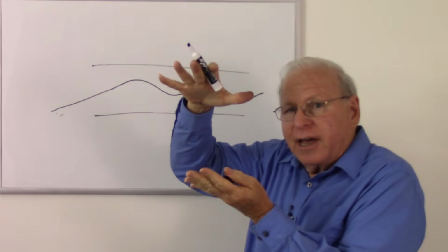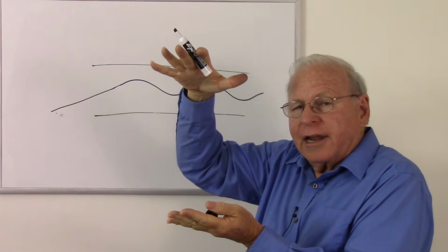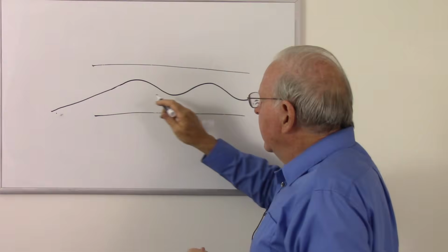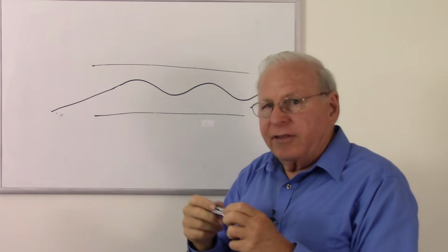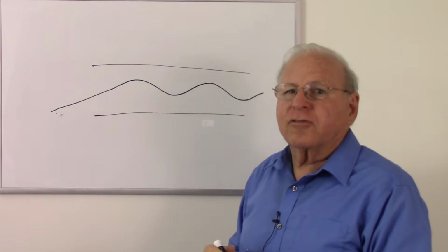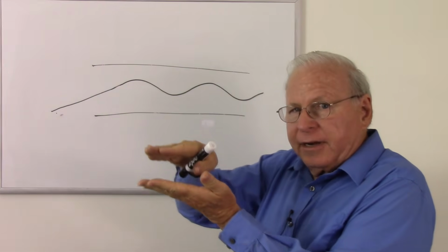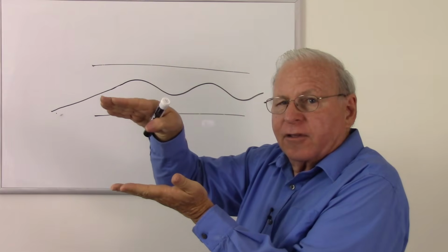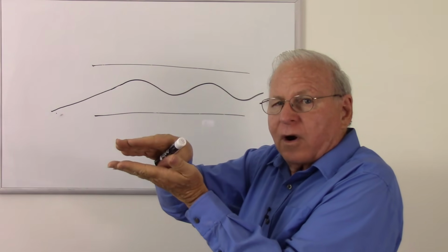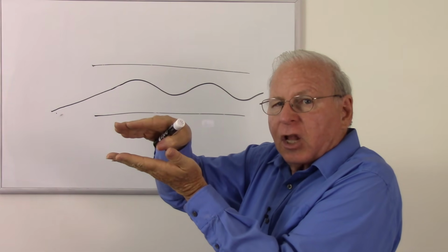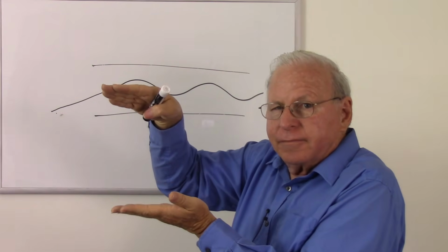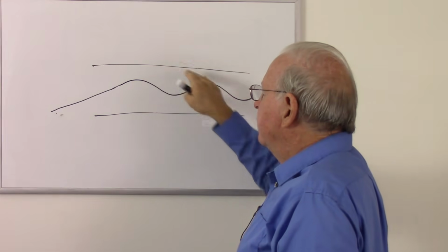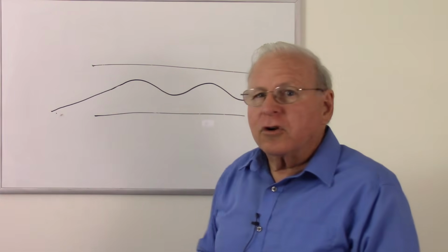So that actually confines the modes to a smaller area. So it's a lot like making a smaller core, but this keeps the waves near the center. And so this also mitigates the modal dispersion that we already talked about, and this is called graded index. So we have step index, which goes one index of refraction, lower index of refraction for the cladding in the core. Graded index means that the core has a high index of refraction in the middle, lower and lower toward the edge, and then finally a cladding of a much lower index of refraction to make sure that any light that does manage to hit the edge reflects back in. So that is called graded index fiber.